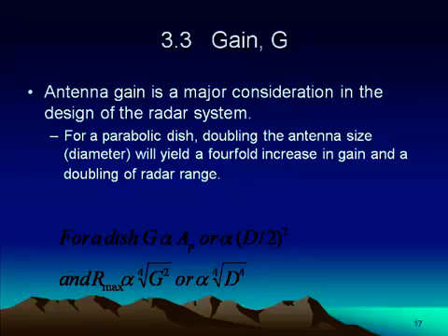the day-to-day activities. Like improvement in radar power of the transmitter, you need to spend more money for that. But if you want to improve the gain, you need not spend much on that. So definitely the radar designer will try to see that the antenna being used has the highest amount of gain. That is why a parabolic dish is the popular choice.